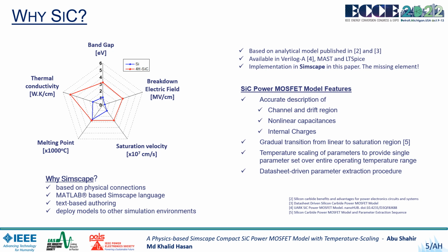Based on the analytical model published previously, there have been models in Verilog-A, MAST, and LTspice. We have implemented the silicon carbide model in Simscape in this paper, which features accurate description of the channel and drift region, nonlinear capacitances, internal charges, gradual transition from linear to saturation region, temperature scaling, and a datasheet-driven parameter extraction procedure.